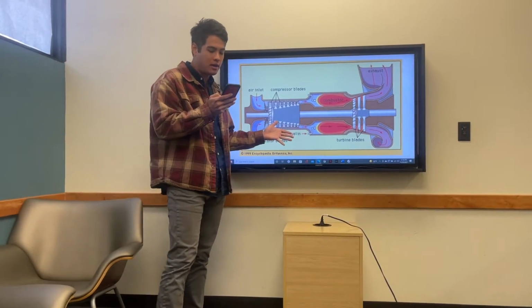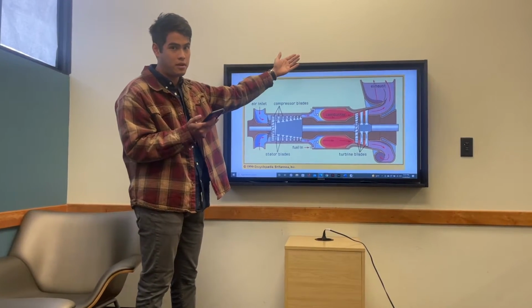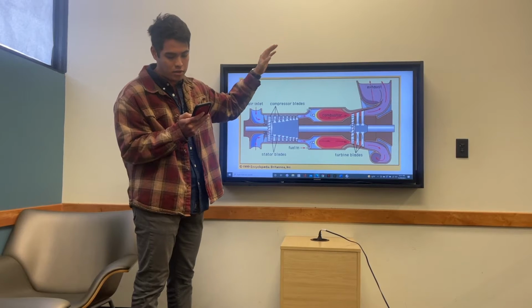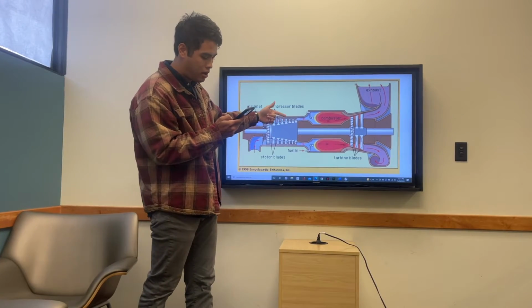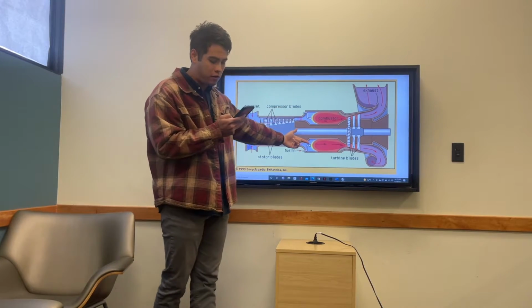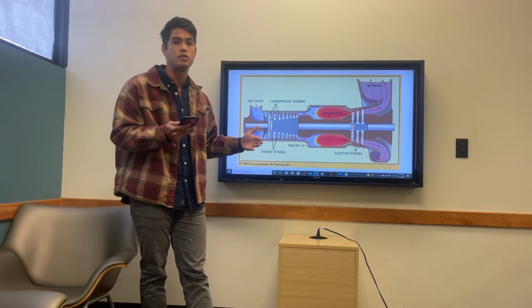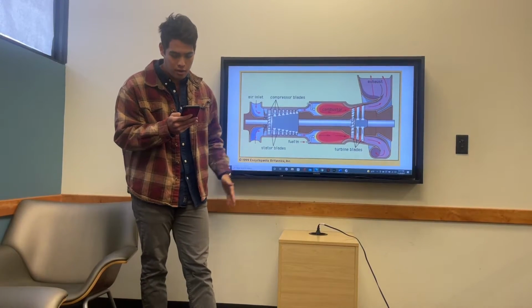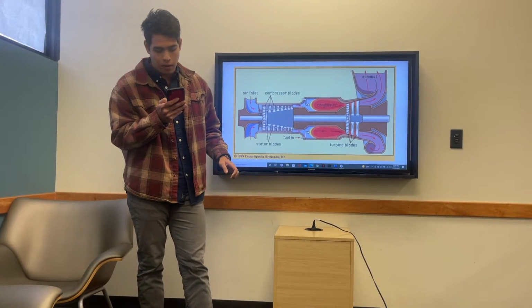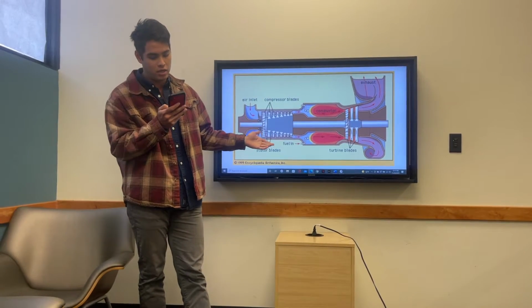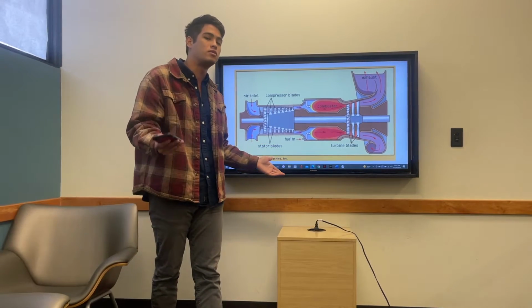And then next, in the third stage, the isentropic expansion stage, the compressed heated gas enters into the turbine area where it expands, and as the gas expands, the pressure and the temperature reduce, but the entropy remains the same. So in this process, the gas works on the turbine and it turns the turbine blades. The blades rotate, operate the crankshaft, which further moves the vehicle wheels, or is able to produce mechanical energy in terms of a crankshaft. And finally, in the isobaric heat rejection phase, the unused heat of the gas expels via the heat exchanger, the temperature of the gas decreases, but the pressure remains unchanged.